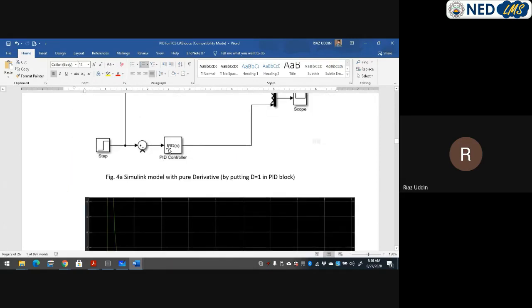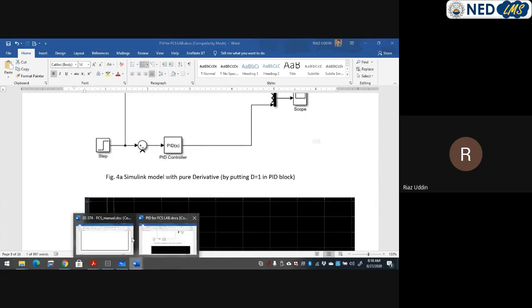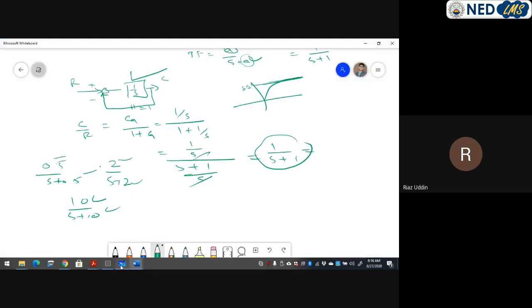Now I'm using a differentiator function of PID, because the ideal differentiator tells something very interesting. You cannot sometimes make an ideal differentiator. If you make a simulation block and put s, it will always give you an infinity error. Because x2 minus x1 divided by t gives you the d term, the s term, but usually this t is very small.